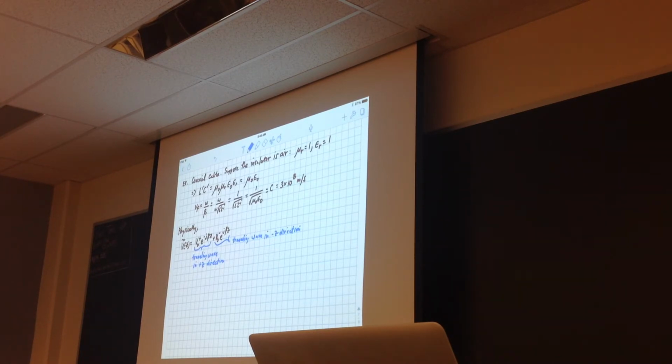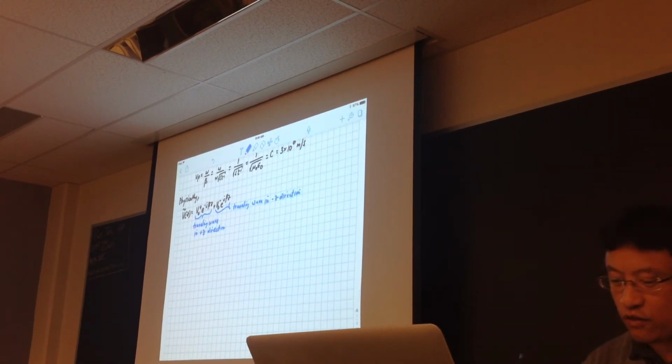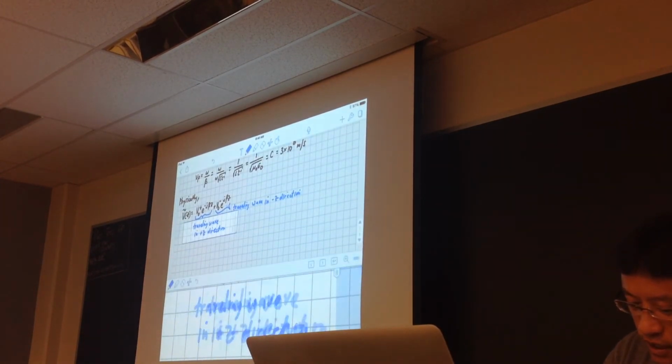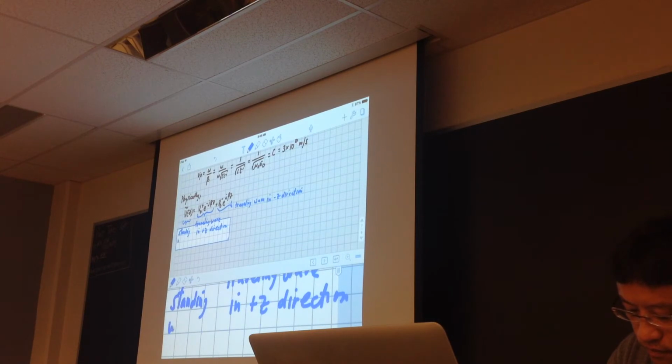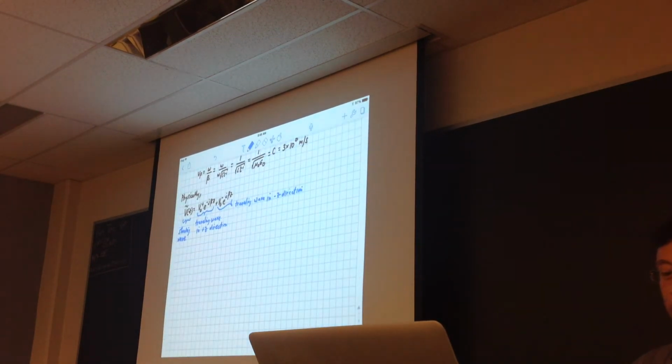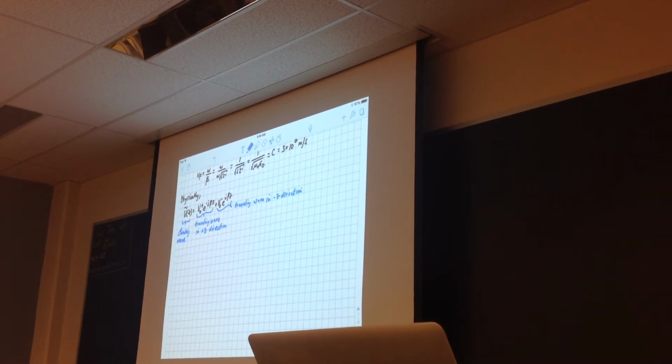So the voltage expression that we have here really represents a standing wave. Okay. So these are standing wave solutions in the same kind of way that you have standing waves on a guitar string. You have standing waves of voltage on your transmission line. So V of z represents a standing wave. And you can get all kinds of standing waves depending on the ratio of V0 plus to V0 minus.